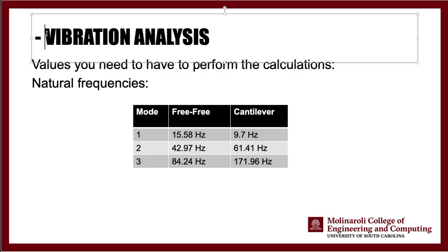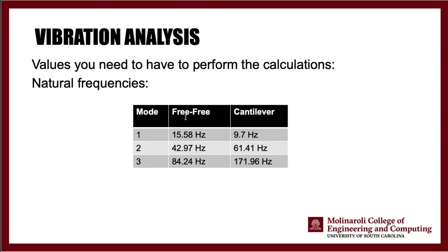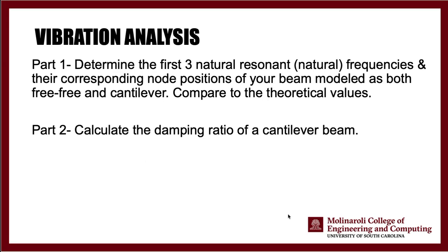But all of the natural frequencies you need for the free beam theory and the cantilever theory are given to you. And again, the idea would be for you, for the first part, to use the first 3 natural frequencies, natural resonance, and their corresponding node positions, and compare them to the real measurements that you have in the lab. Part 2 is going to focus on writing the LabVIEW code. The idea here for you is to learn how to write a LabVIEW code as well, and then find the damping ratio of the beam.